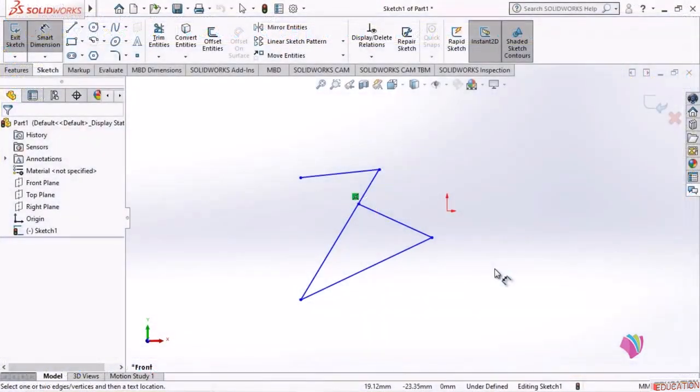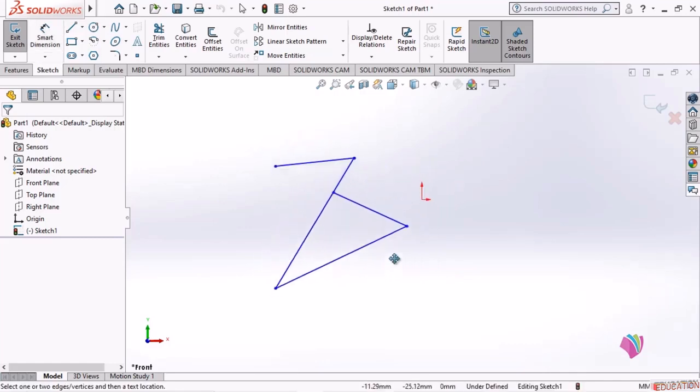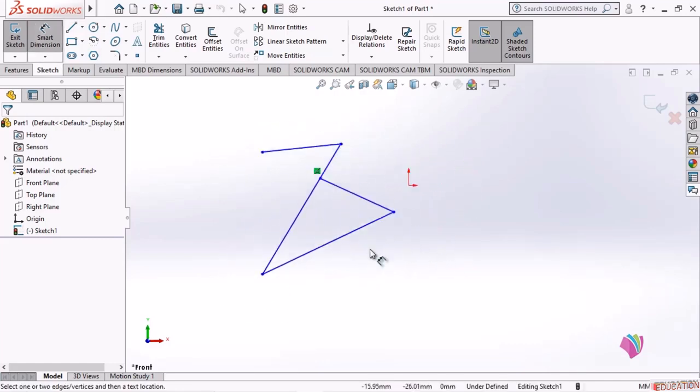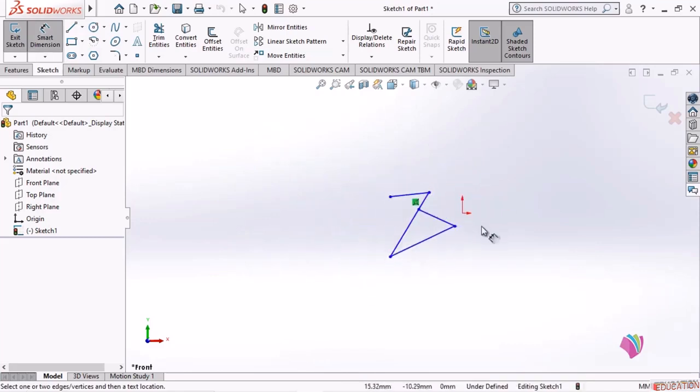Now in Solidworks, you can see we have this profile that we made in the last lecture. Now we are going to use the visual tools. Directly we will see the shortcut tools because that is the way you should work in a CAD software. For pan, you have to use the control key on the keyboard. You have to press and keep it pressed, and press the scroll of the mouse. This is pan. Now if you rotate the scroll, this is zoom.